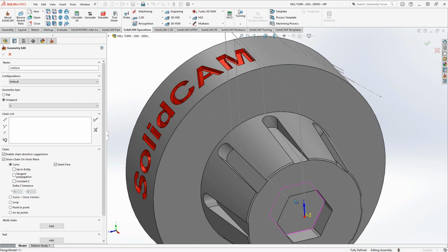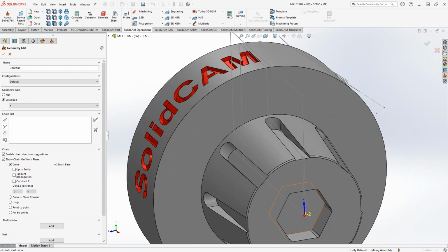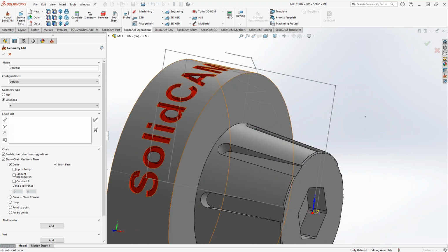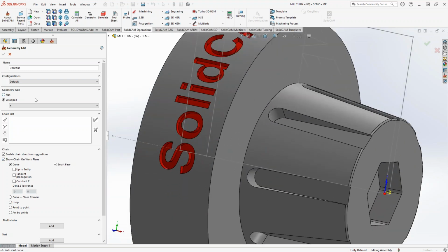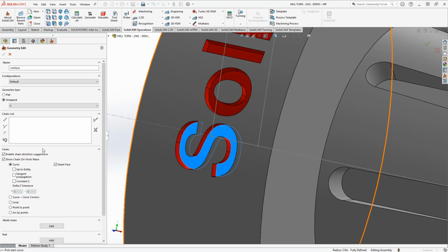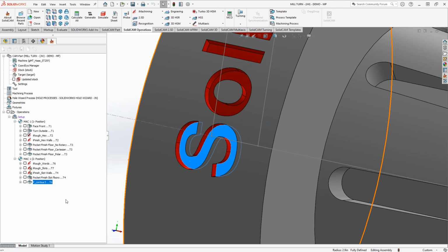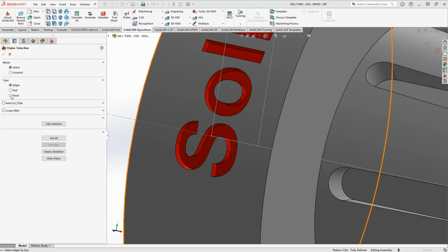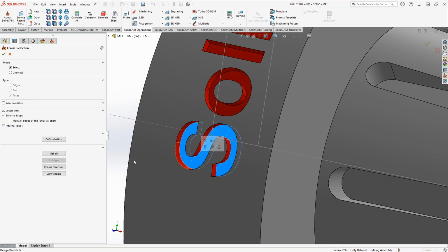And then even though Z is pointing that direction, we're talking about doing a wrapped toolpath. We're talking about having a tool come from the radial direction. So it really doesn't matter if I choose a pocket over here. It's still in the radial direction. So what we'll do is wrapped around X, I will just choose, let's say, an edge off that pocket, and then I can do my constant Z and tangent propagation. I can turn those on if that would make sense for me. I can do my next button, or what's really cool is with the smart face, I should be able to just grab that face, not smart face, but let's go down to multi-chain, the precursor to smart face, and maybe just grab that face like that.